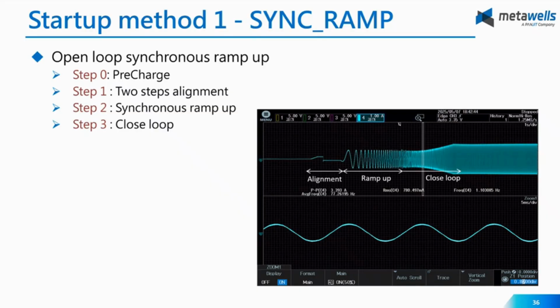Okay, let's start by looking at the current waveform to demonstrate the traditional startup method. This waveform is a very traditional startup method. Startup method one is also known as open loop drag or synchronous motor startup. The first step, step zero, is pre-charge, but we cannot see the pre-charge on this waveform.